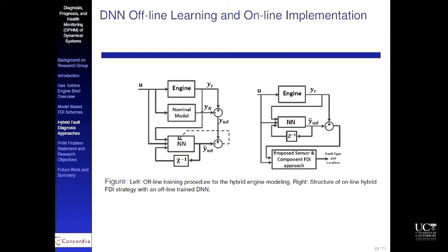So we have the actual process, the engine. Then we have a mathematical model of that, which could be your onboard engine model or whatever mathematical model that you have of that system. What we are doing is taking a difference between actual engine data, actual system data, and the data that you generate from your mathematical model. The difference of these two signals represents the unmodeled dynamics, what was not modeled. What was not modeled here, but is present in the system, will then be manifested in your unmodeled signal.